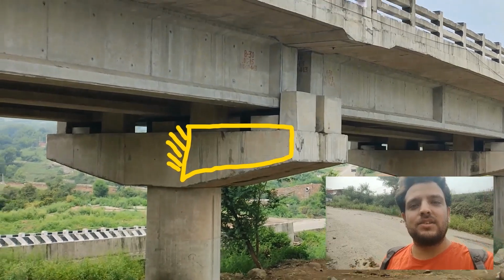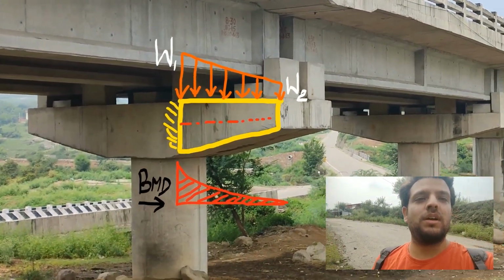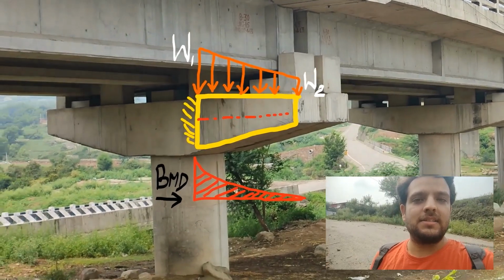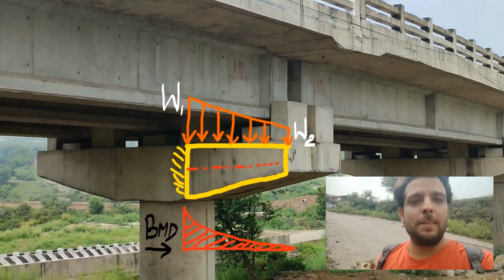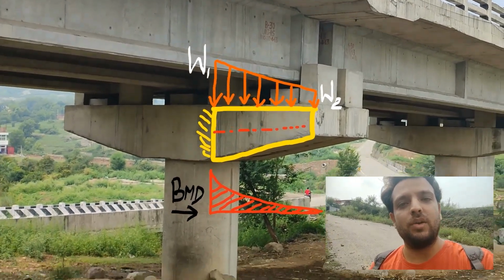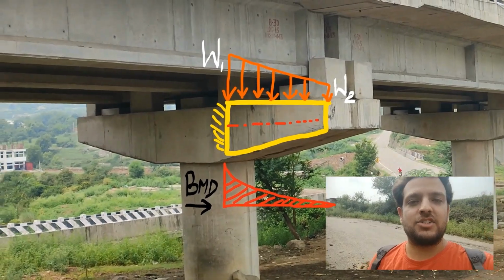Notice that this is not a prismatic section, as it is tapering from the root to the tip, and hence has to be analyzed as if a single cantilever beam is subjected to a uniformly varying load with maximum intensity at the root and minimum intensity at its tip.